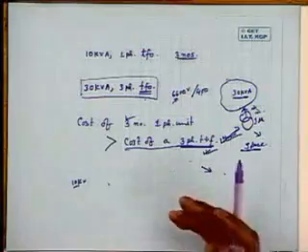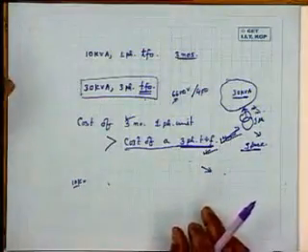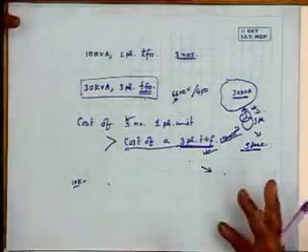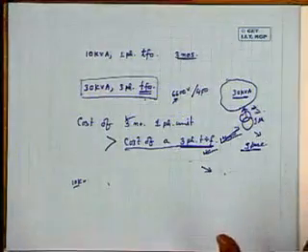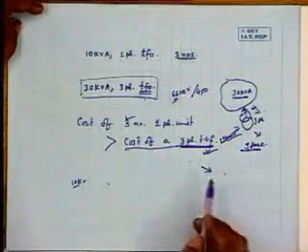Suppose A phase develops a fault. It is not fair to energize B, C phase, supply power some way and at the same time maintain that winding. You have to take it out fully or put it in service fully. There is no other way.